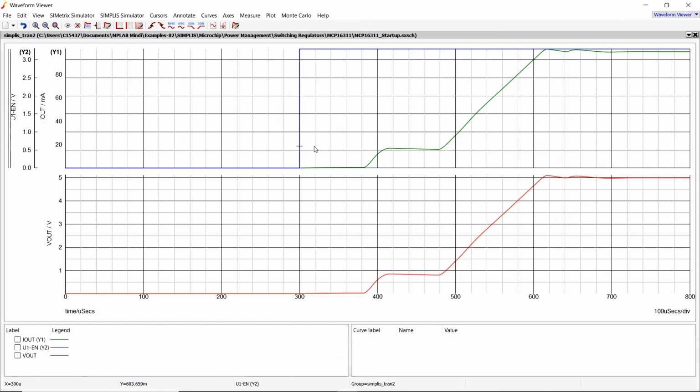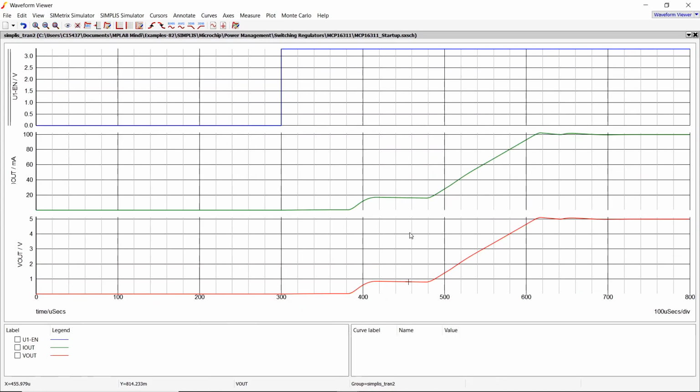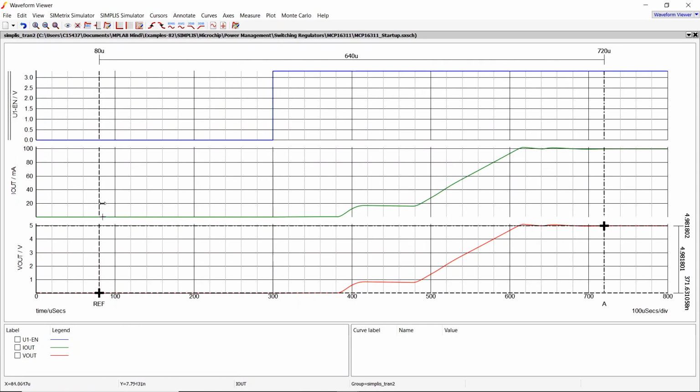And what's the significance of the measurement you're about to show me here, MD? That's a very good question. This is telling us how long it takes for our circuit to be up and running. So I'm going to stack it here before I get into that question. So let's measure this value and then we'll come back to that. Okay. To measure it, we can use the same principles as you would in an oscilloscope. You can go to your cursors, you can pull them up right here, or you can press C on your keyboard. Got 2 cursors going, so let's find out.